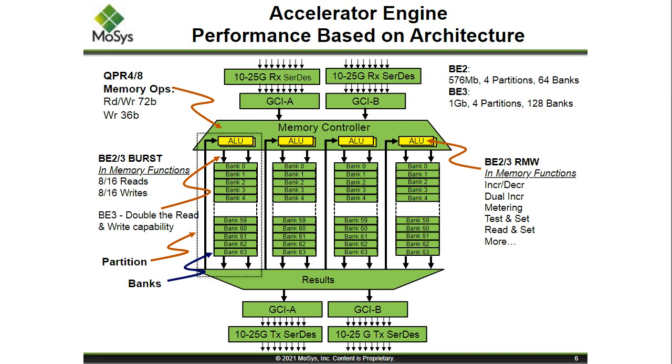As Gus mentioned, we have this interface protocol that we defined as gigachip interface. So we've used this interface because it's designed specifically to interface with memories. It's a low latency, high efficiency protocol that you could use on a SerDes lane. And so again, they're divided into these two blocks of 8 SerDes each. So a total of 16 SerDes, allowing for the RX and TX both down the bottom.